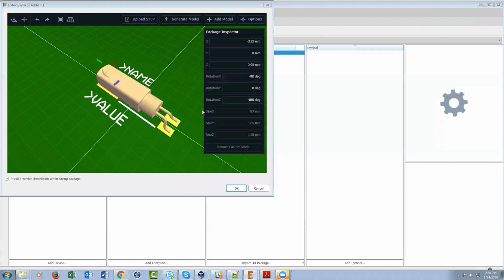I can build my footprint and symbol, but get no option for a 3D model. Okay, so when that happens, that would mean that you haven't made the library managed. You have to make the library managed in order to get the option. As soon as you do, you get the same name as the footprint showing up in the 3D package column, and then you can assign it. So that could be what's going on, Sean.